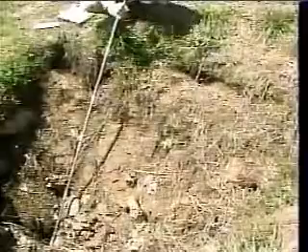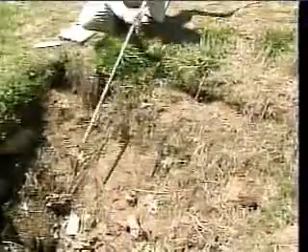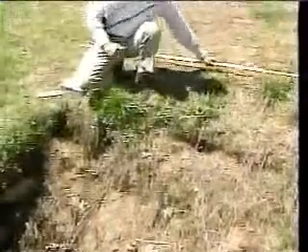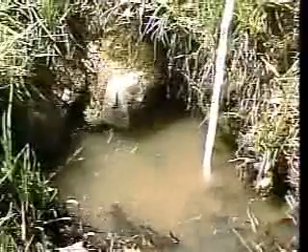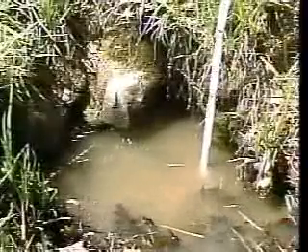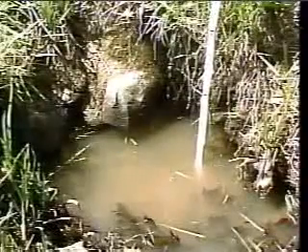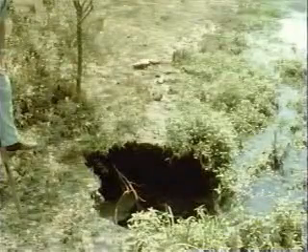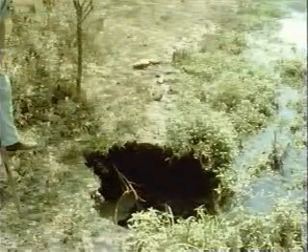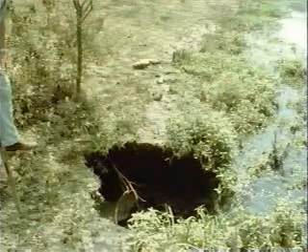Probe a sinkhole for the presence of a larger void below the apparent bottom of the sinkhole. Check for running water in the bottom of the hole. Remember to photograph and write down the size and location of the sinkhole. Don't forget, get an engineer to look at the situation as soon as possible.